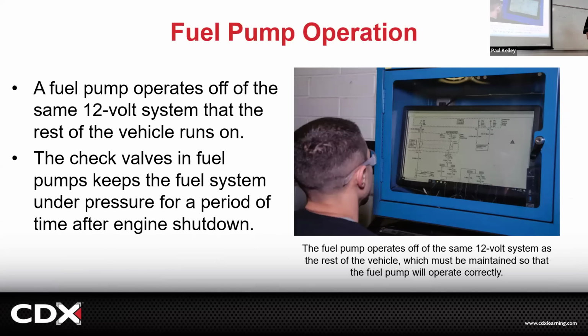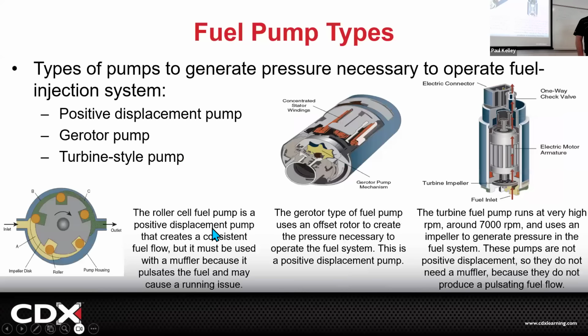Alrighty. Oh, and I knew I had a little note right here about the check valve. The check valve in the fuel pump keeps the system under pressure for a period of time, right? So it's there. Then when we get into the actual pump, some of this stuff won't be extremely critical, but you know, all the pumps have a mechanical and an electrical aspect.